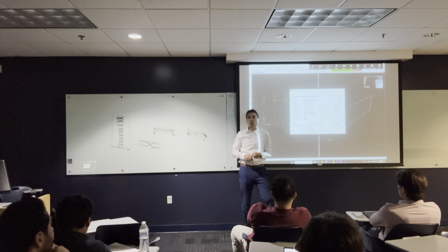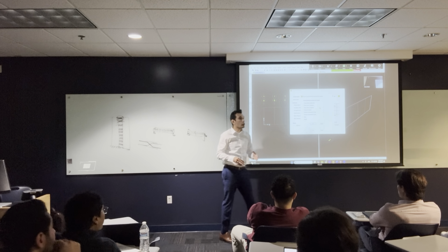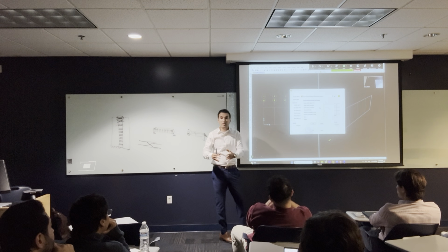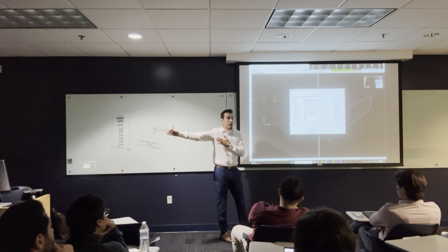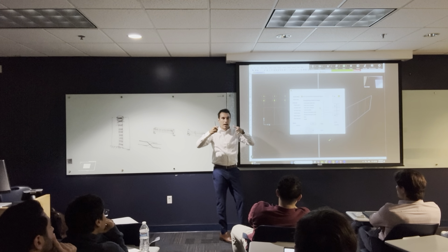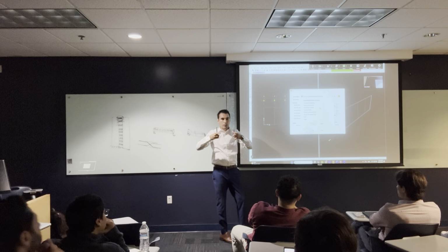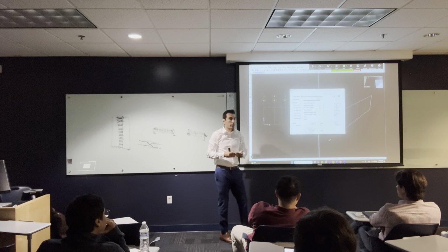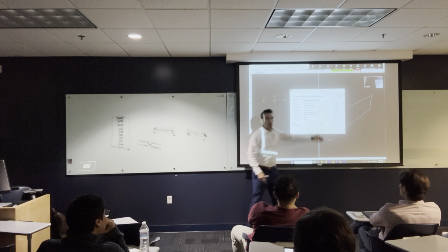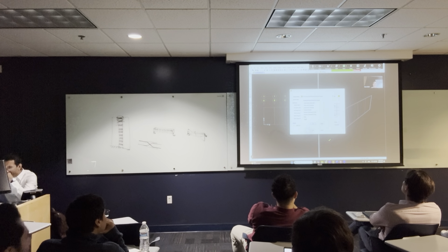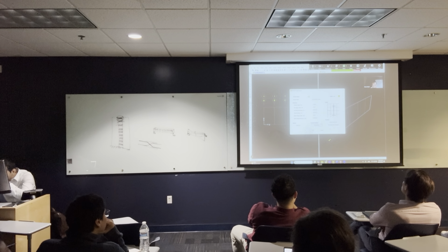And sometimes when we work, I'm not sure if you guys, maybe in the future, you're going to work with retrofitting of a structure. So you go to a 30-year-old bridge or a 50-year-old bridge. So it's all cracks everywhere. So if you want to have the cross section of the column, you cannot use the full strength of the column. So you have to reduce the stiffness of this column. Okay? So we can do this here in the set modifiers. And there's some stuff that we're not going to touch.